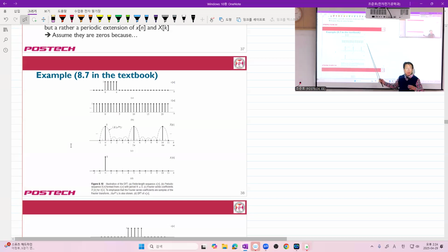So we have an all one signal. And we know from our signals and systems knowledge of DTFT, the DTFT of this signal is what? A periodic impulse. We can interpret this as a periodic impulse with period 1. So the so-called sampling function or comb function in the frequency domain.